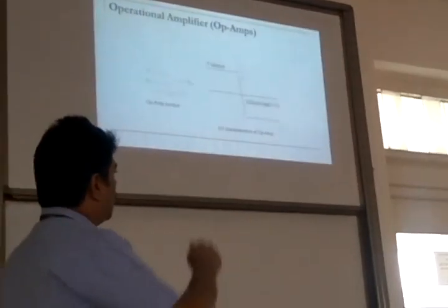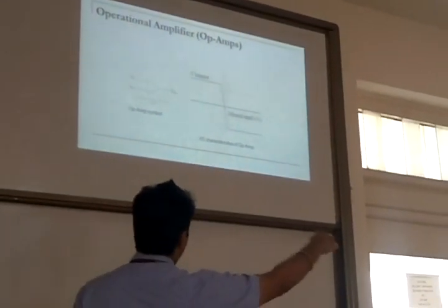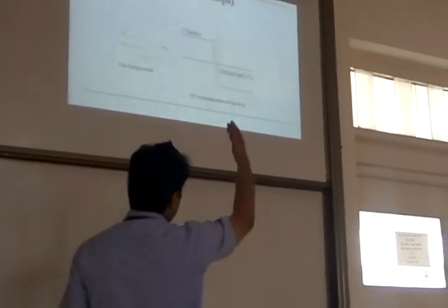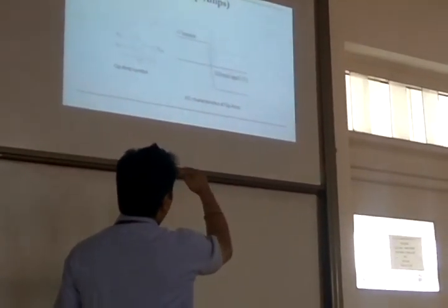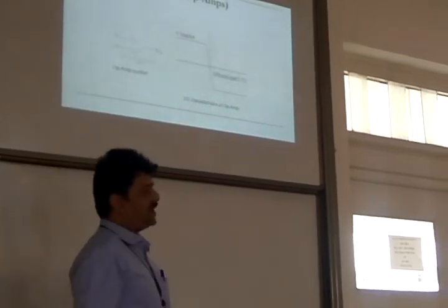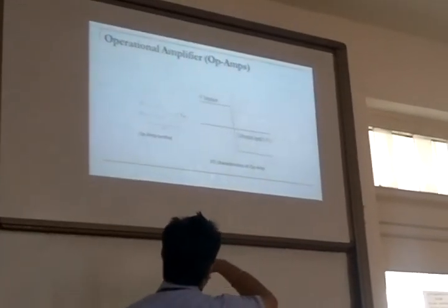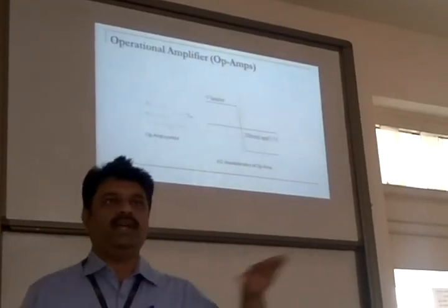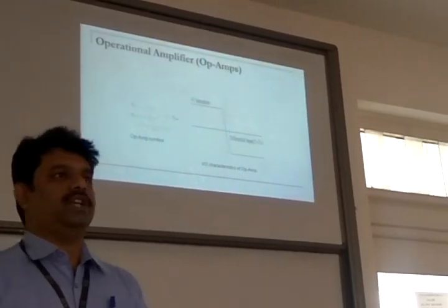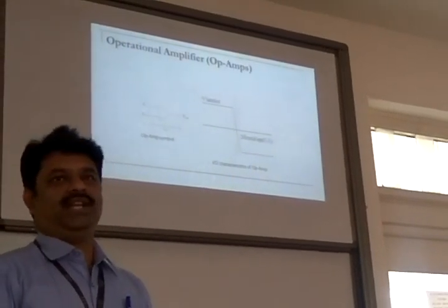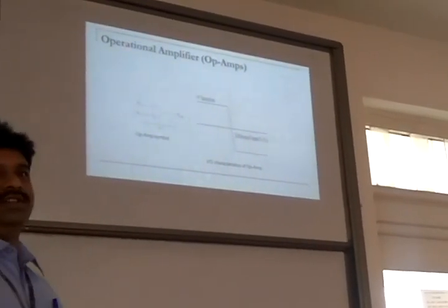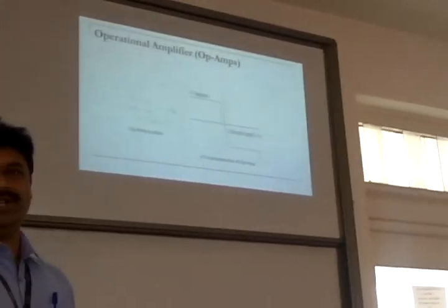It's saturation. So on the negative side, there is a saturation. Similarly, on the positive side, when the difference is negative, you have positive voltage output coming out. That's on the left side of the vertical line, and that also reaches a maximum, which is saturation on the positive side. So you have the input-output characteristics for the operational amplifier.